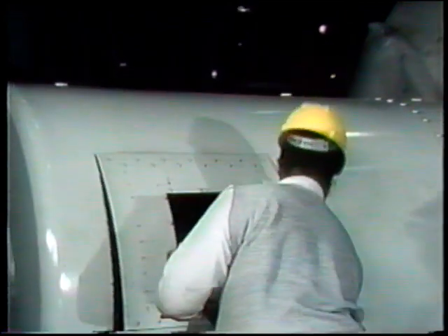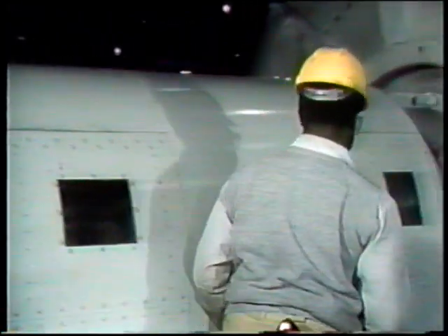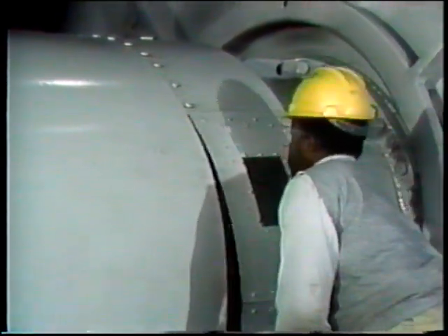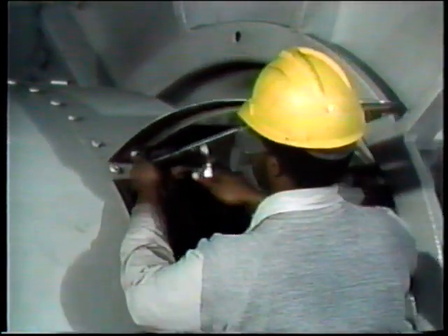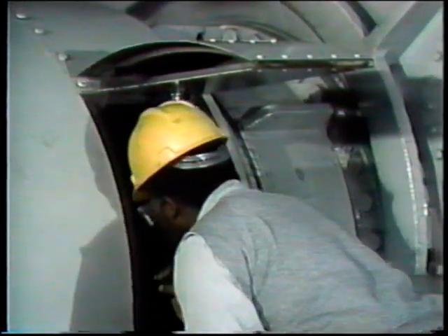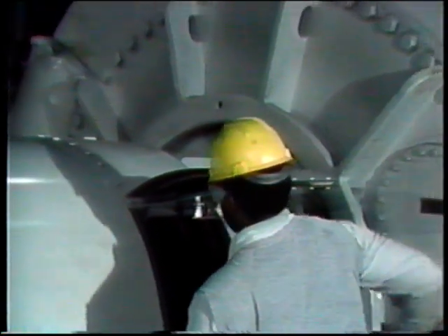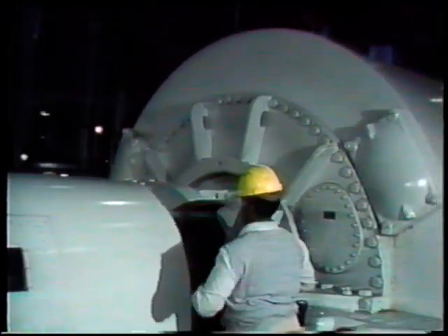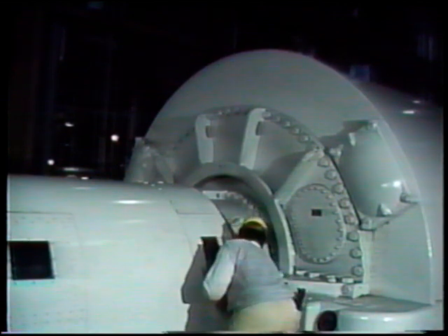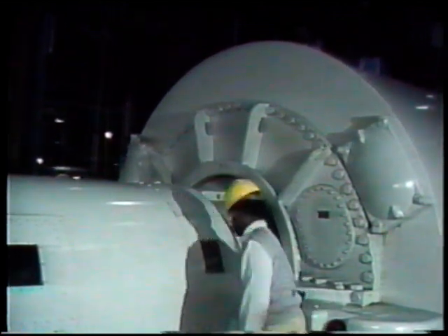After the electrician finishes checking the rest of the main exciter brushes, he moves on to check the brushes on the generator's slip rings. He follows the same basic inspection procedure. He carefully checks each brush for contact with the slip ring and keeps an eye out for anything unusual. Well, it looks like there's only one brush that needs replacing on this side of the generator. The electrician has to check the brushes on the other side of the generator as well. Then, he'll go and get as many replacement brushes as he needs.